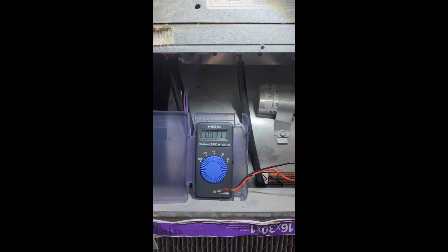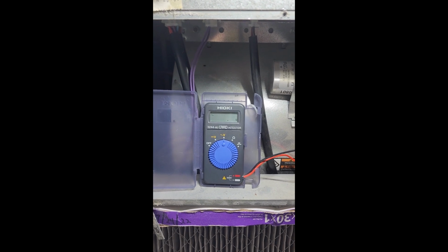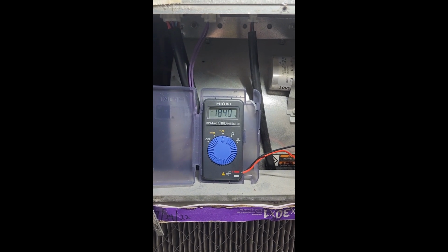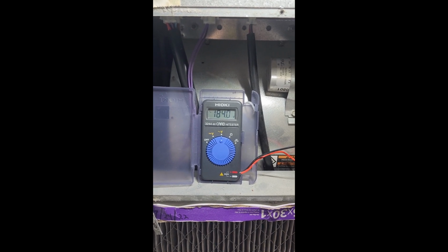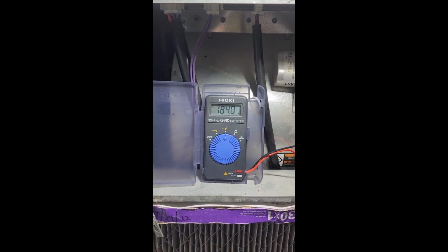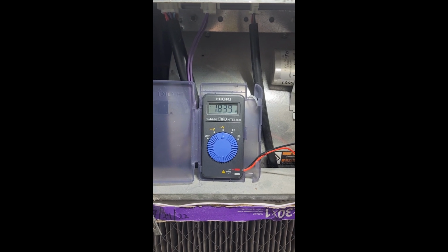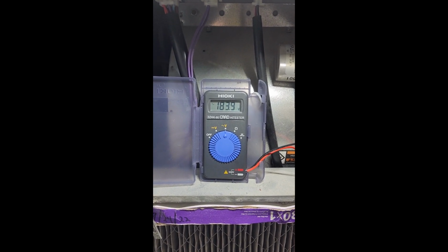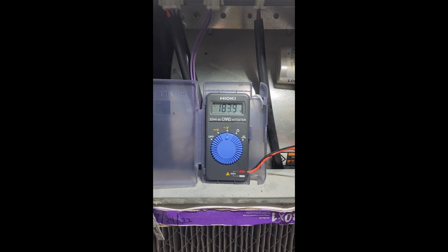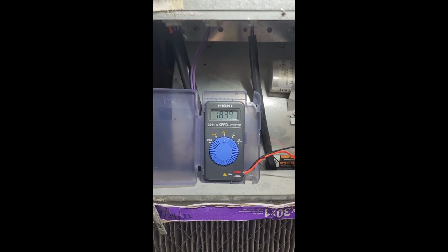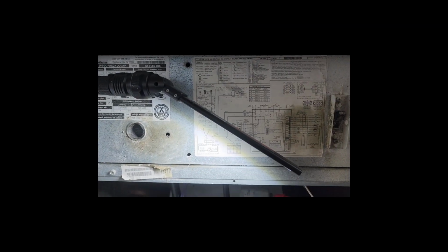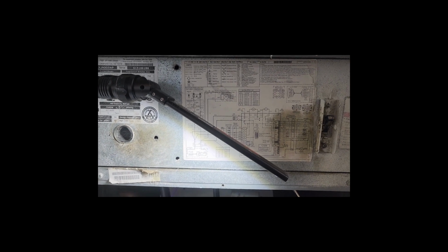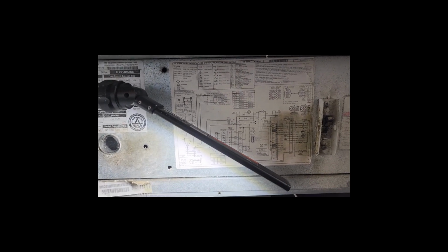And we are going to find out together what happens when I turn this breaker back on. So let us see. Now, so it looks like we have some good AC going to the contactor, or rather the startup capacitor. So we can, from this, pretty much eliminate anything in this box. So we, I think, are pretty close to a diagnosis.